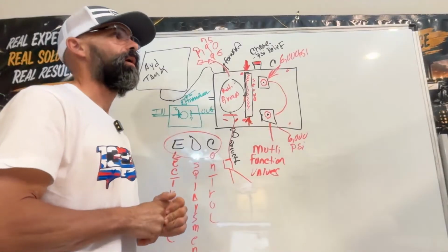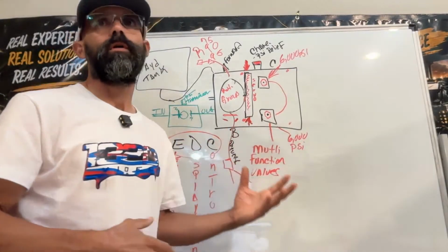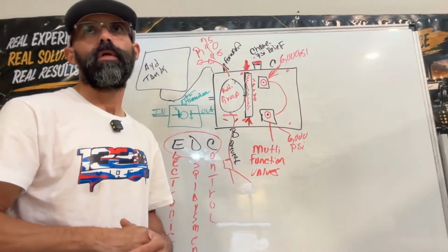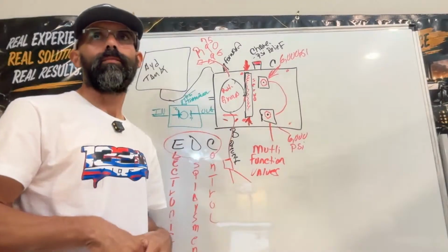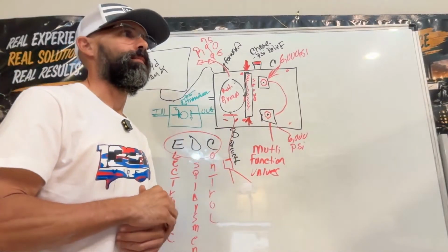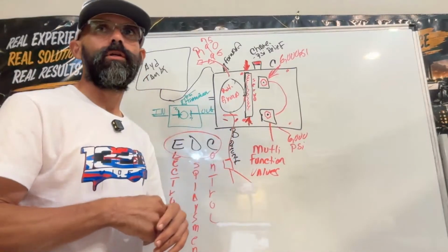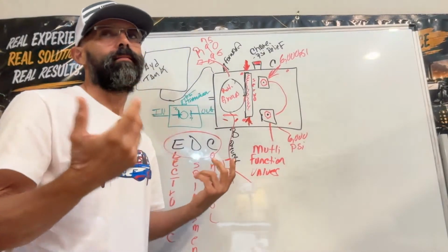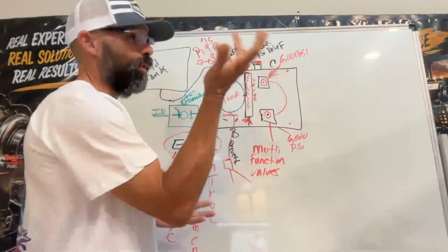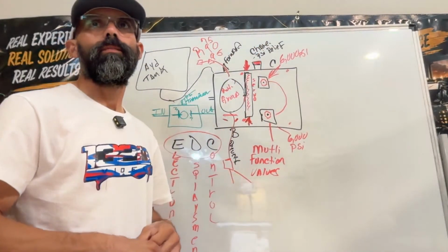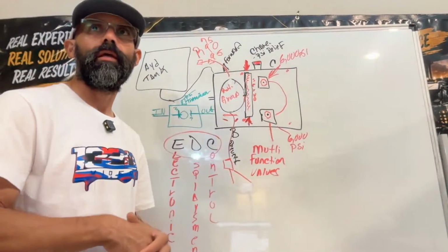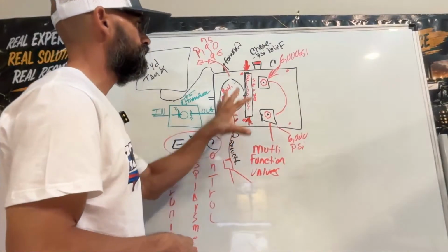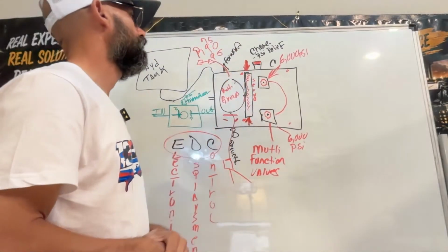We're not perfect. The service technician can be working on it, replacing filters, and then he drops the brand new filter and it gets full of dirt. He's going to try to blow it out, or if he has an air compressor on the truck, he'll try to blow out the dirt, just driving that dirt deeper into the filter. Then he puts it back in, and that dirt is going to loosen up and go somewhere, and then catastrophe. Something might get blocked off.